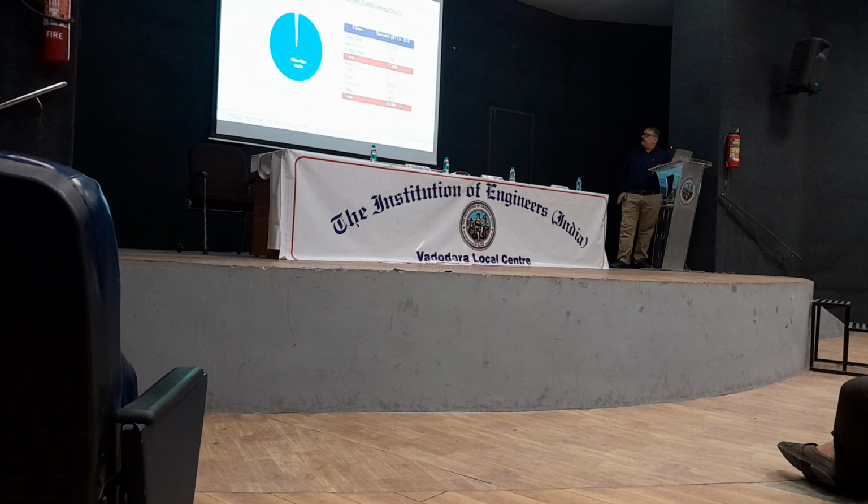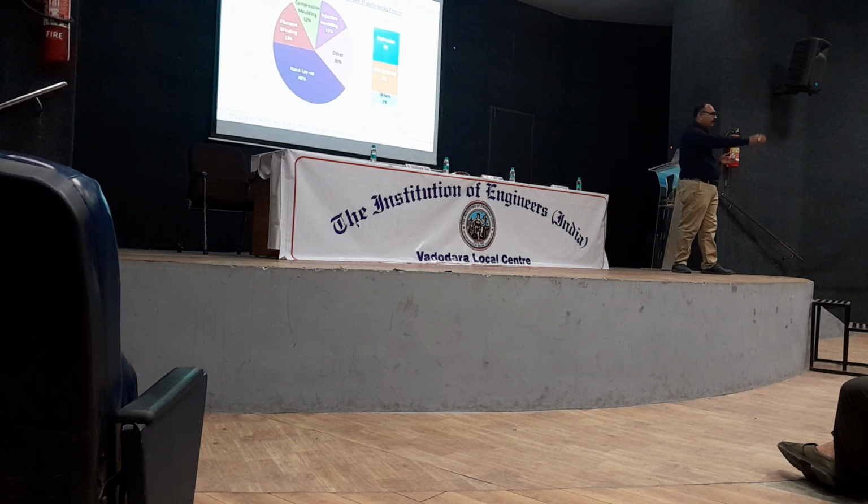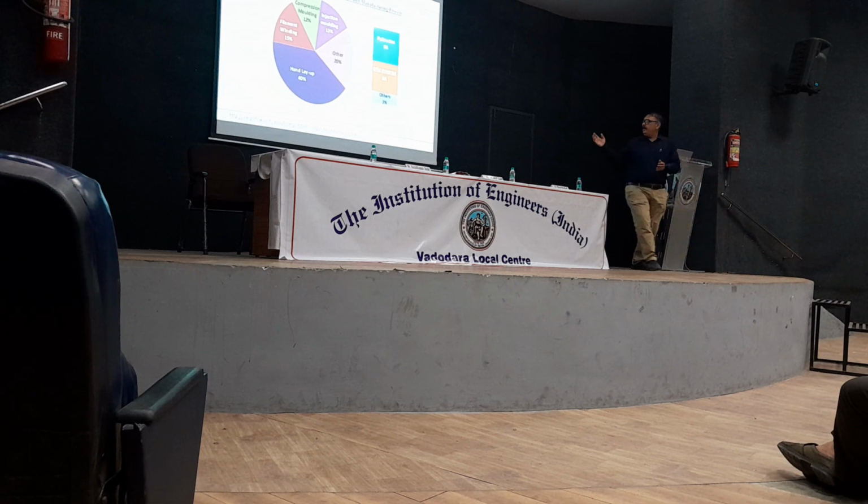These are the manufacturing processes. This is the resin market, and mostly pultrusion. Some of the people may not be aware of what pultrusion is. Continuous sections are prepared, for example an edge section, continuous or whatever it is. Then RTM, resin transfer molding, and vacuum assisted resin transfer molding. Most of the people right now in small scale industries are using hand layup.